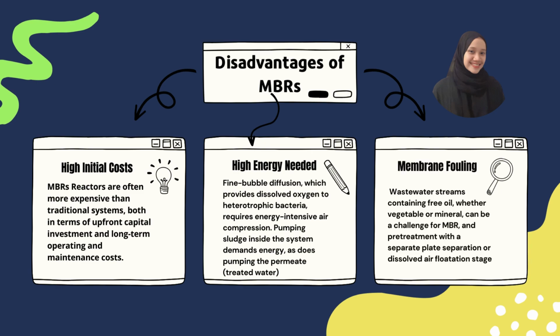Lastly, membrane fouling. MBR membranes frequently clog owing to membrane fouling. Wastewater streams containing free oil, whether vegetable or mineral, might pose a problem for MBR, necessitating pretreatment with a separate plate separation or dissolved air flotation stage to prevent membrane fouling. However, adding an additional stage may raise costs and negate the benefit of the MBR's tiny footprint.